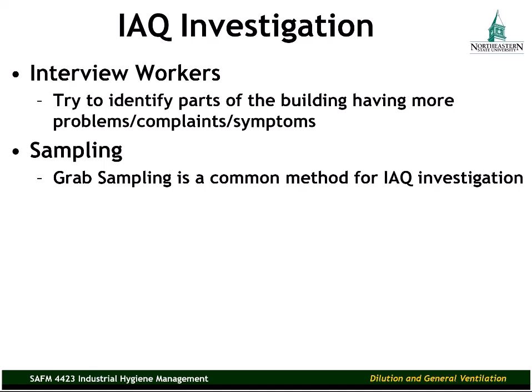Don't just take one sample. Well, I guess if it's a small area like one office, one sample would probably be sufficient. But if it's a larger area, like a whole group of offices, take a sample from each of the offices. If it's a floor of a building, take samples from different areas on that floor.